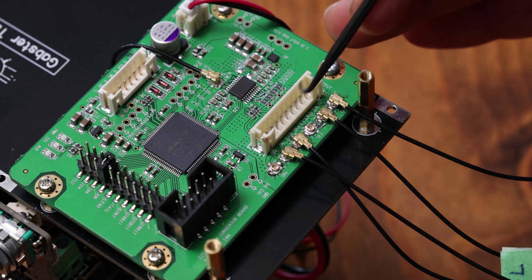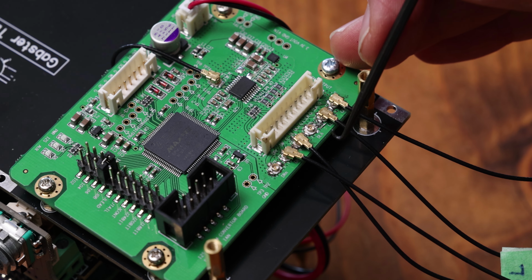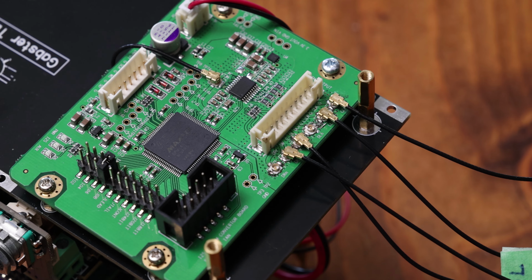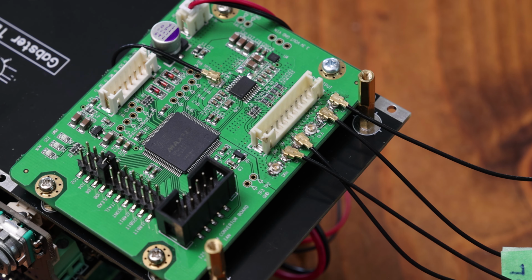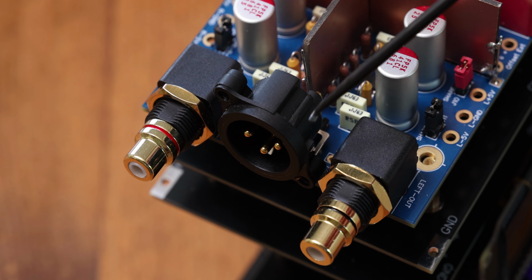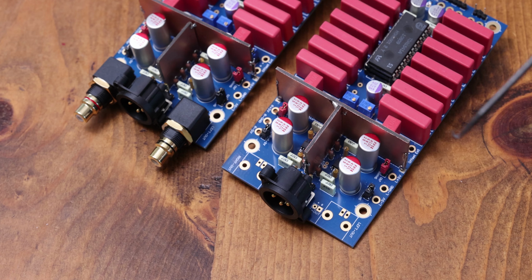And then you're going to get DRN and DLN for the second board, and these are going to go respectively into the DL and DR of the second board. And now you have an inverted signal for the second board, and together you're going to make a balanced connection. So in balance mode, you must use the XLR connectors on each board, and each board becomes one channel. One board becomes the left channel and one board becomes the right channel.